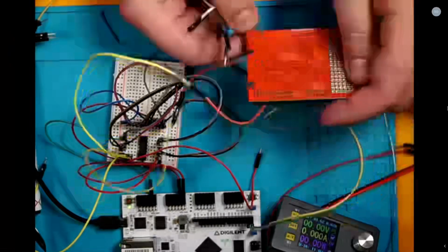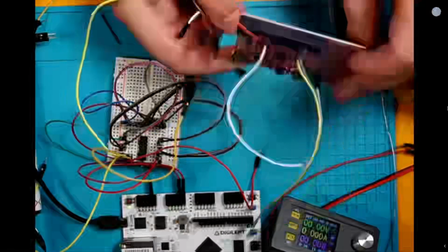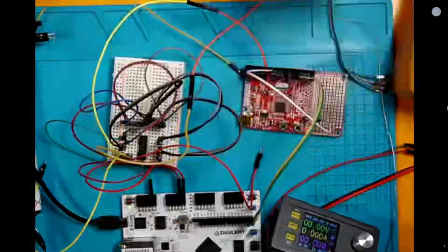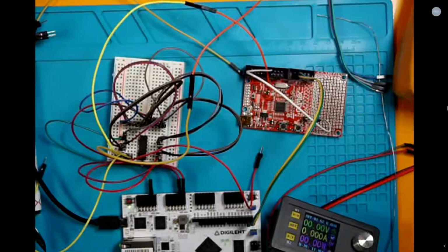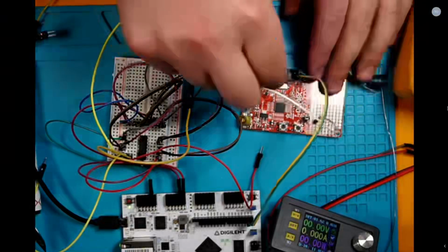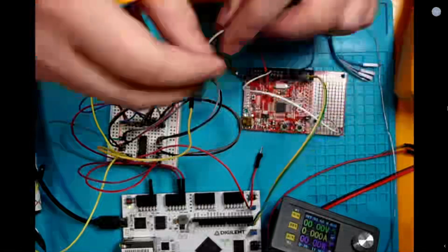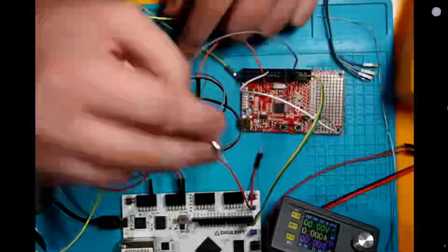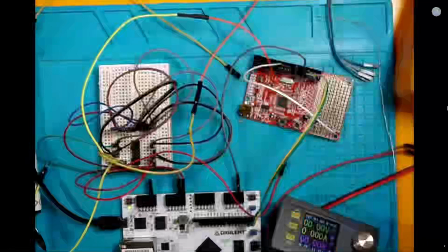And I mean, we can also take a look down here. So the ground, I'm pretty sure it's the outer one. That's the ground plane, if I remember this board correctly. So let's connect this guy to ground. So we can also connect to the FPGA. So we have ground pins over here. And so we should be good to go.